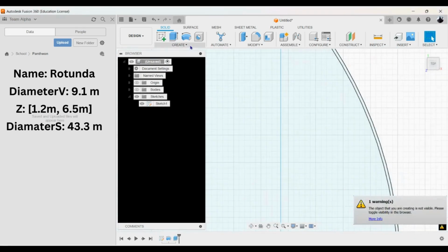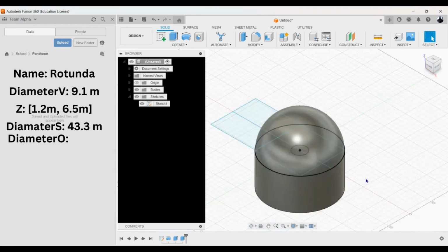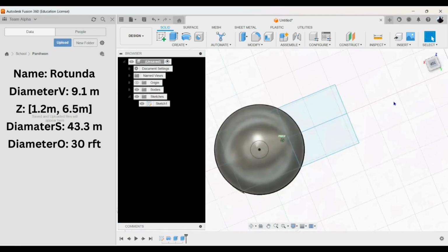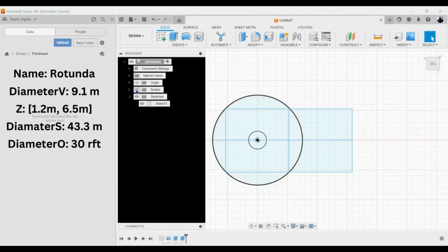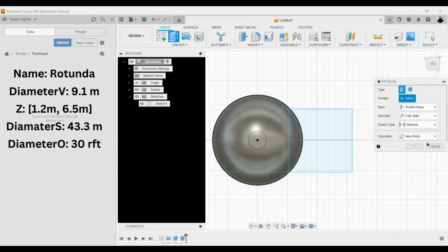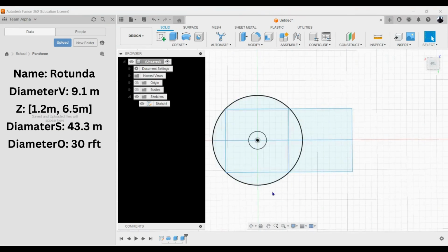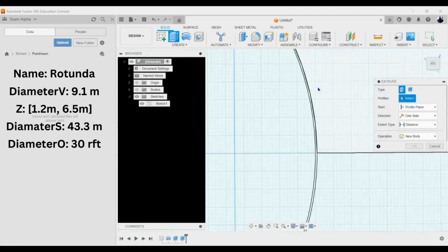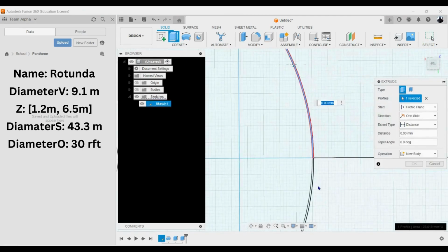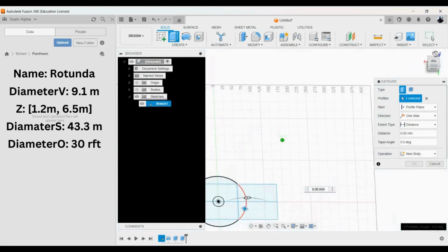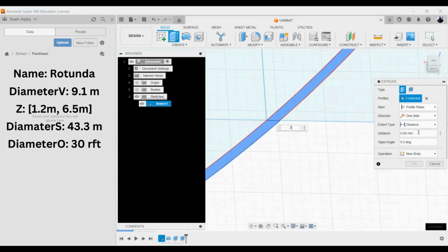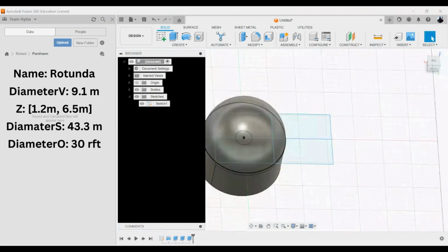When expressed in ancient Roman units, the dome spans 150 Roman feet. The oculus has a 30 Roman feet diameter. In this CAD step, revolve the half circle into a half sphere with equal radii for the circle and cylinder. This becomes the inner sphere for developing thickness with another radius. I messed up the other half of the cylinder because I forgot to set up my 2 points on the cylinder and sphere to be the diameter.